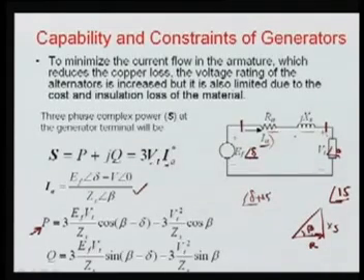So this is also called the impedance angle. The real power can be related by this expression, and the reactive power can be denoted by this one. We know that the reactance is very high compared to the resistance of the winding, because normally we use a very pure conductor. Conductor means we use aluminum or copper. Normally we use copper in machine winding, so the resistance is very small.